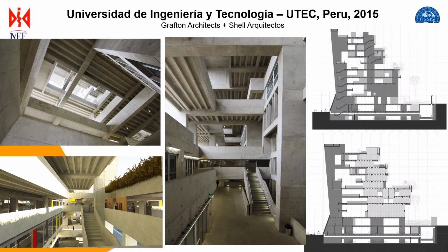Due to the use of seismic isolation, this building has complex and atypical geometry and characteristics for seismic zone, an irregular structure in plan and height. Plans have large openings in the diaphragms. All levels are different.